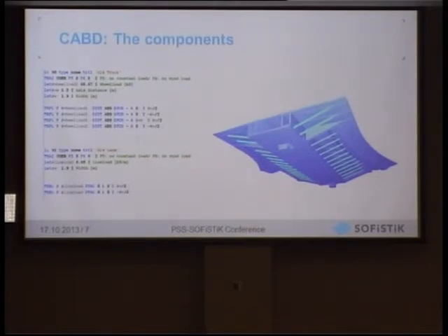And we see here a detailed model where we used one part of the bridge and remodeled it as a shell model, because it's a very wide deck, and it also has leaving lanes, so two lanes leave the deck to the left and to the right. This model was also generated using the axis concept, but we have a lot of different axes, because we have one main axis which is straight and two additional main axes to model these exiting lanes, and all these lanes have some secondary axes.